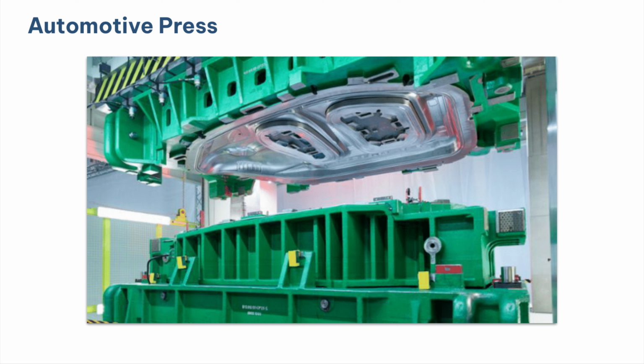An automotive press pretty much only has one option. That's going to be a continuous online monitoring system. The number of changes of state and the continuous monitoring is the way to go so that you can collect data when the machine is in the same state every single time for trending and proper analysis.